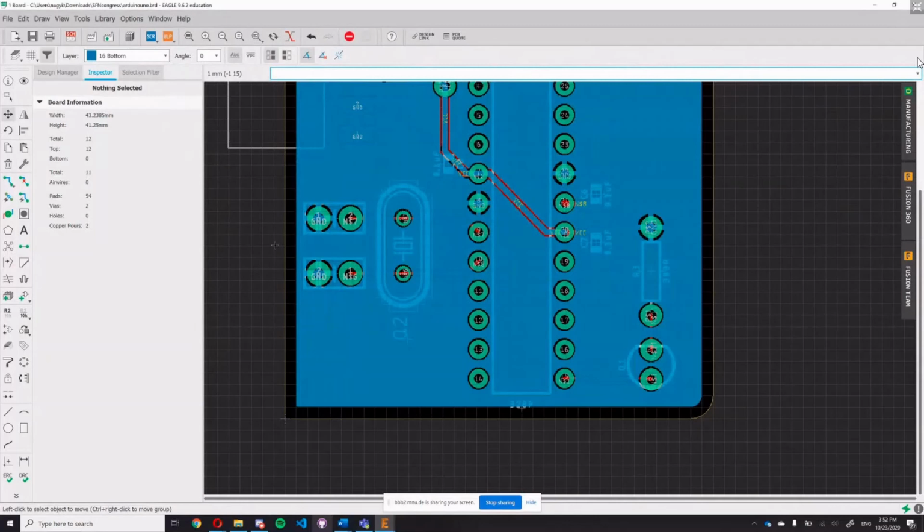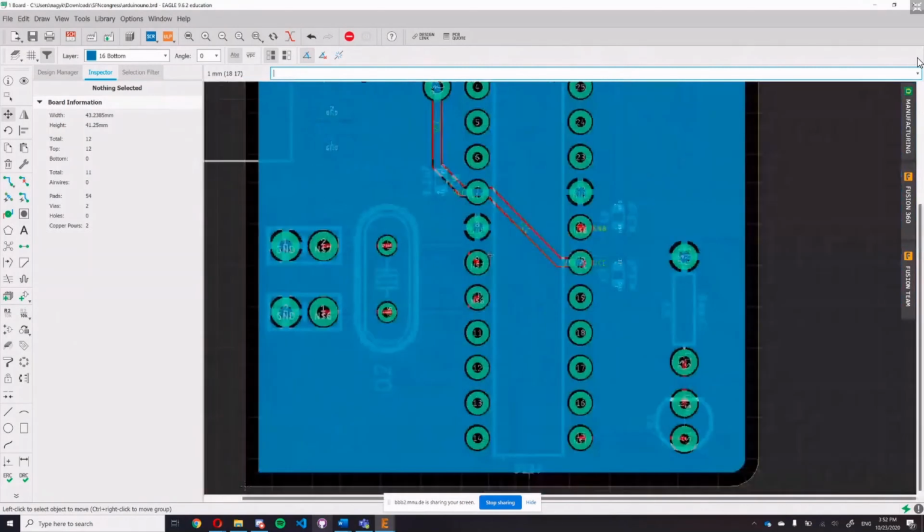But there's also an issue because the ground is separated. So you have two different panels of ground, and two different sheets of metal not connected in many spaces is not good. So it can work as an antenna, as a capacitor, and it can have adverse effects.